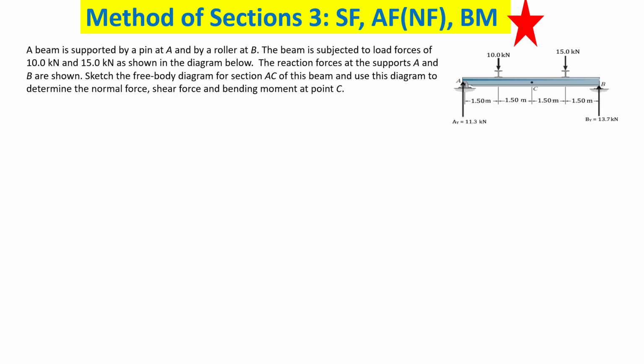Just keep going. So it's given in this question. Now we are going to draw the bending moment, shear force, axial force diagram. That means the internal forces. First thing is, you need to section the beam and find out where to section it. So you go along the beam, and you can see loading conditions are changing at these points. Am I right? So you need to cut: first cut, second cut, and third cut. So you need to have 3 sections.